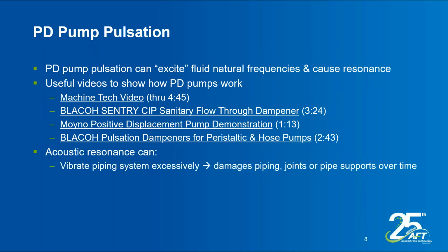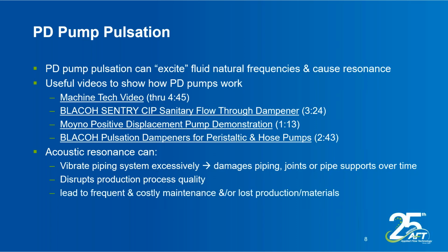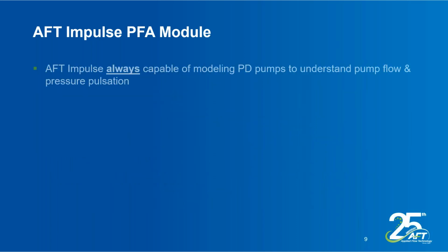So when you have that acoustical resonance, it can cause your piping to vibrate just like in the videos, and destroy your piping or your joints or pipe supports, and it can certainly disrupt your production process quality. So certainly something that you want to make sure that you avoid.